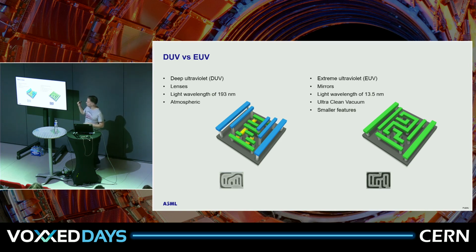Then what we saw until this far is mostly about EUV. So with EUV, we use mirrors instead of the older machines with DUV that use lenses. And we need those mirrors because if you use lenses, EUV light is absorbed. So then you no longer have EUV light and we cannot use it. With EUV, we can print smaller details, basically smaller transistors, but it's also possible to print features that require 3 layers in DUV. We can print them in 1 layer with EUV. So there are a lot of advancements in new generations of machines.